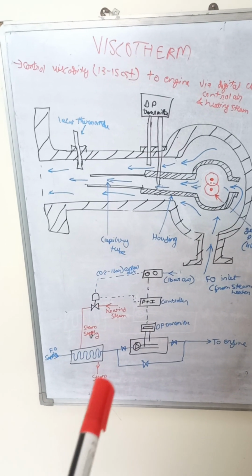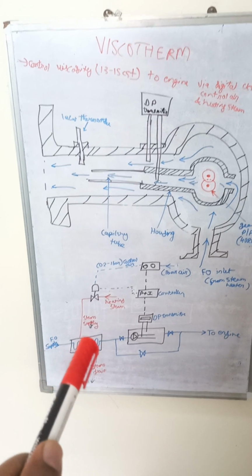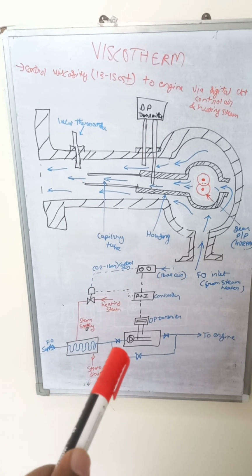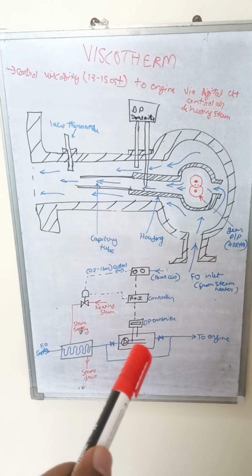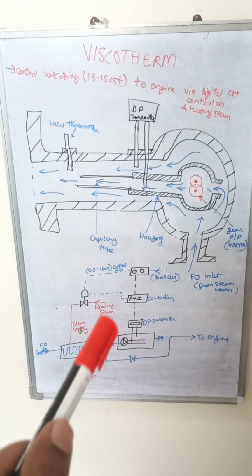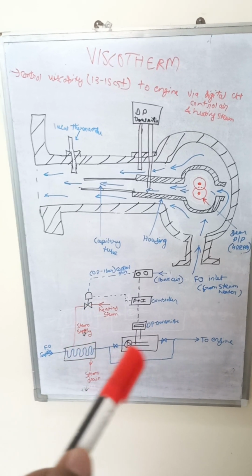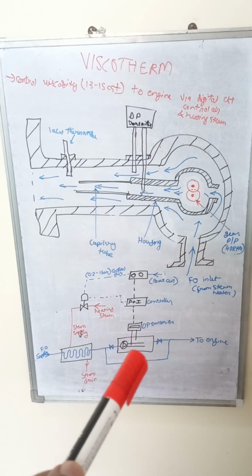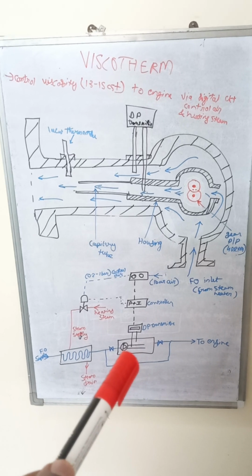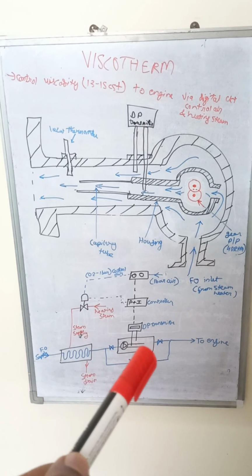This is the block diagram for the digital circuit. The fuel enters the heaters, and after the heater it will enter into the viscotherm device, but the fuel needs to be heated via steam. So we will control the heating by the steam via this circuit. The pressure in the capillary tube pushed by the gear pump and the pressure outside of the housing will be measured.